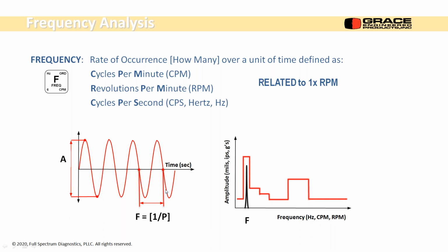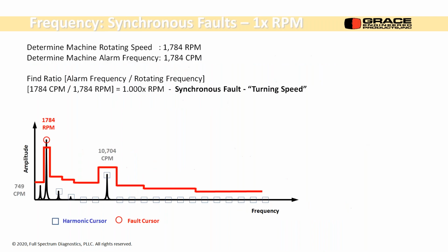But as we talked the other days of this series, how do you calculate a frequency from a time waveform? You have to encapsulate the entire period in time. So we start here, we go to a negative maximum, we go to a positive maximum, and then we go back to 0 and repeat. If we know that periodic event, frequency is 1 over the period. If it took 2 seconds, then it's 1 over 2, it's half a hertz. Pretty easy calculation, real easy for the FFT processor as well.